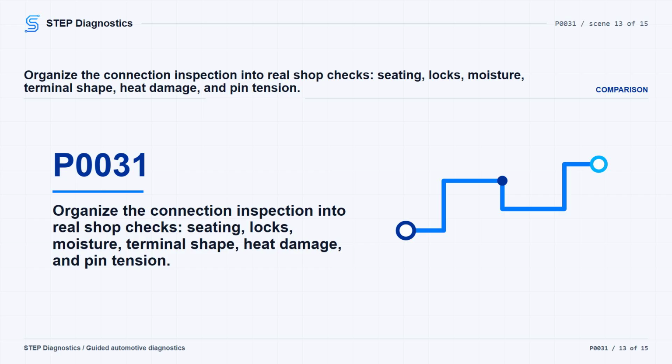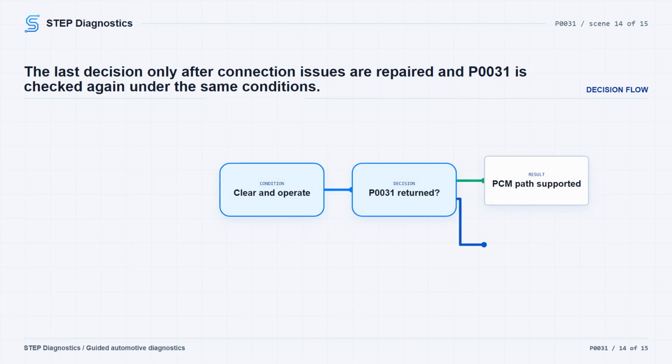Look for poor connector installation, damaged locks, corrosion, signs of water intrusion, damaged weather seals, bent terminals, overheating from a poor connection, terminals pushed back in the cavity, spread terminals, and poor terminal tension. Repair any condition found. Then reconnect the PCM connectors, inline connectors if equipped, and component connectors, making sure everything is fully seated and the locks are fully engaged.